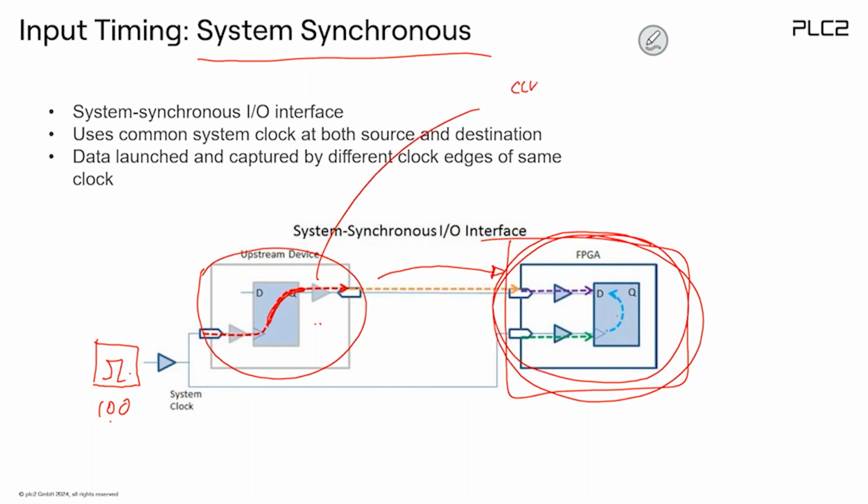So this is the clock. Let's call the signal Q. What happens in the real world? You can also get this information from the data sheet. Signal Q looks like this. After the rising edge, after a while, the signal Q will change. It will be unknown, we don't know. Then it will repeat again. And for the next one, this would be the period T of the clock.